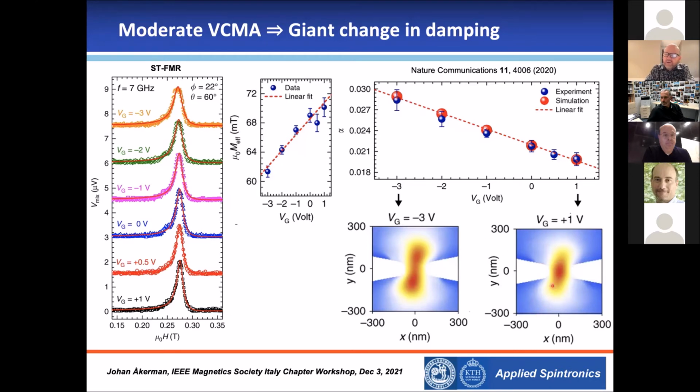And then when it's more contained, it interacts less with the far field, and it still has the same drive. It's still being driven by the same current. So it feels less dissipation with respect to the spin Hall drive it has. That leads to a much lower dissipation. So it's a combination of a minor change of M effective and a bit of an amplification effect from the geometry that leads to this rather large change in effective damping.